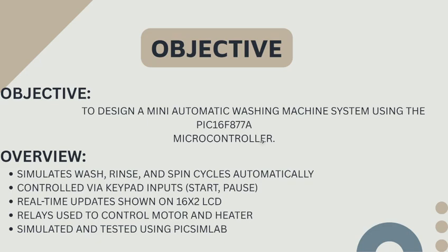The system is fully controlled by a microcontroller. It receives input from the user through buttons, for example, to start or pause the process. The process timing and status are displayed on a 16x2 LCD screen. What makes this setup interesting is the use of a relay to control real-time hardware like motors and heaters.